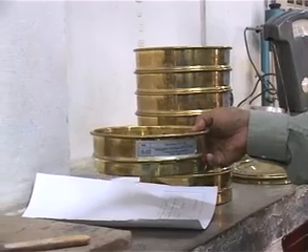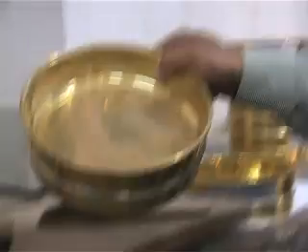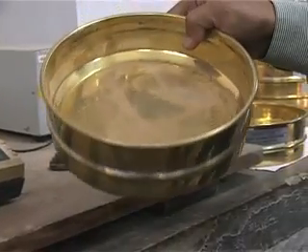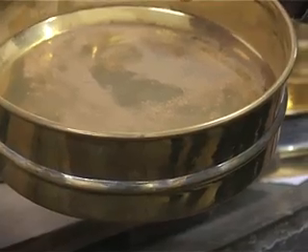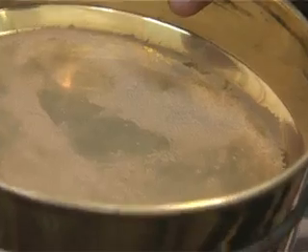Then we are going to proceed to the other sieve sizes similarly, and you can see here that there is a little bit of soil retained past the 75 micron size sieve. The grain size of this particular fraction is typically not determined from sieve analysis. We will need to go on to another laboratory experiment, involving a hydrometer, for finding out the grain size distribution of the fraction of soil which is finer than 75 micron.